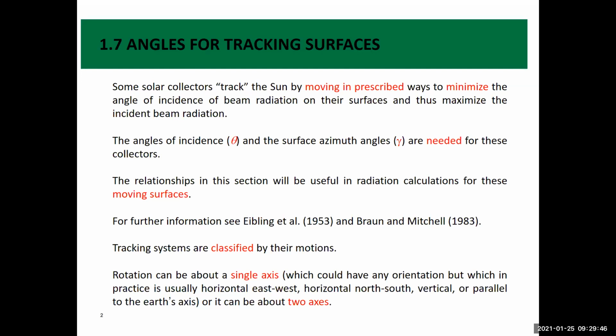And if you are talking about a PV system, you may use part of the energy you are generating to run the tracking. So at the end, is it worth using part of the energy to run your system, or to put the system without this additional penalty of energy from what you generated, and you just keep, or would it be enough what you get from the solar rays or solar radiation in a fixed location? There's no one answer to this. It depends on your application.